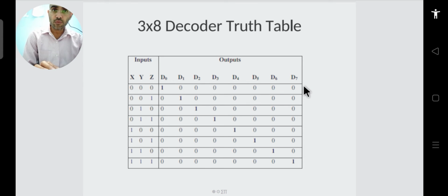So you see, there will be 8 outputs. For the 8 rows on the input side, for each row correspondingly you will have one output. You can write the K-map for each of these outputs to solve it, but it is useless to write a K-map because you can see that in D0, out of all these rows, there is only a single row with a one. This one row will not combine with any other one.